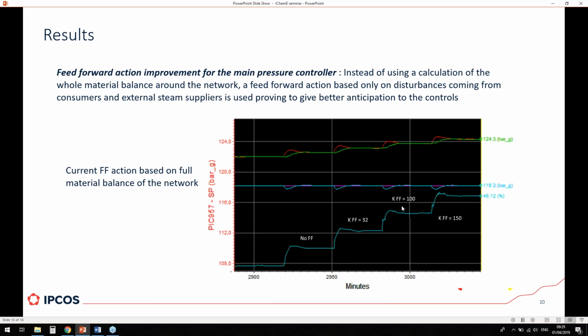It initially gives you a dynamic advantage, but the moment the controller starts reacting, the moment the pressure controller starts correcting, that information then is consumed back again by the feed-forward action. I know this is a bit confusing, and you can contact me later for details about this, but basically it's like a dog chasing its own tail. So it doesn't really work. So for as much as you try and increase the feed-forward action, this is not improving the overall performance.